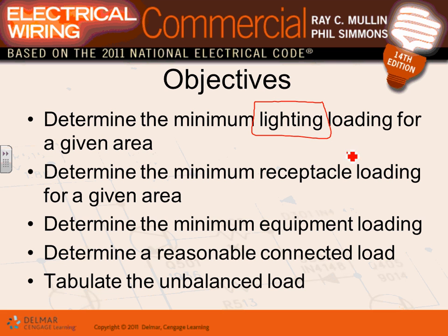And receptacle load. Can I emphasize the word minimum? When you guys do load calculation, everything that you calculate is minimum. If the panel size, Karen, is 100 amp, can I put a 200 amp panel? Yes. Why wouldn't we put a 200 amp where we need 100 amp? Because we don't want to spend more than what we need to, right? Because an optimum design, guys, is a balance between quality design and expense. That's how you come up with an optimum design.